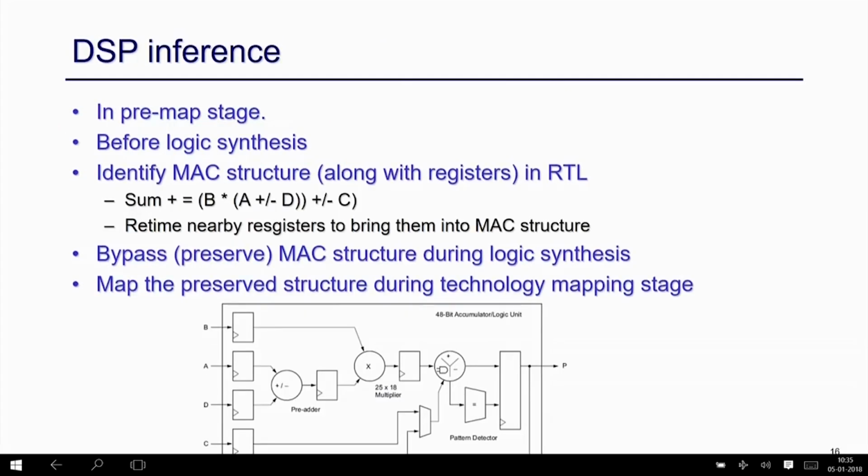Okay. So, let us start with the DSP. As I mentioned, the DSP unit is capable of doing many things. It has a pre-adder, a post-adder, MAC summations, and also 3 sets of registers. So, the objective is to map the maximum substructure into this structure, because if you just do an addition in this block, you are still occupying the whole DSP. If you want to do only one multiplication here, you are also occupying the whole DSP, because this DSP cannot be used for something else.